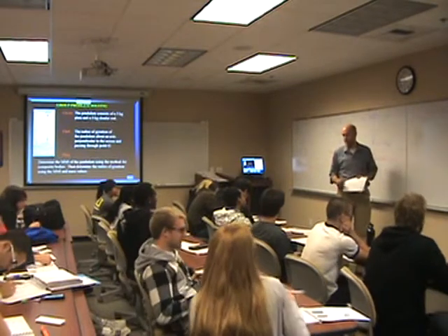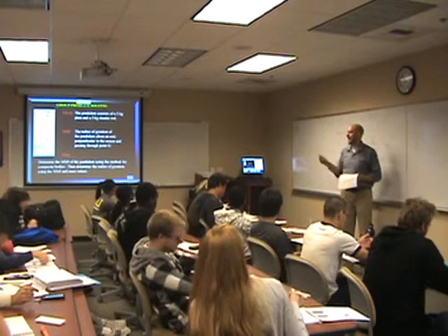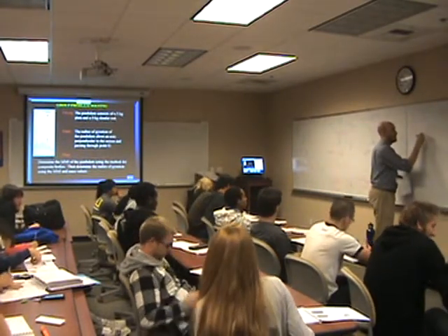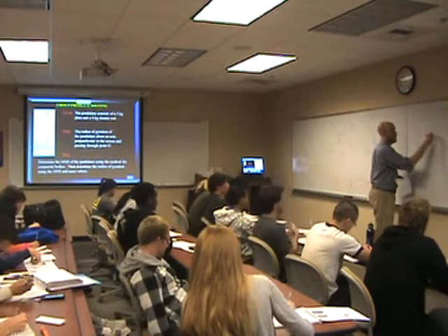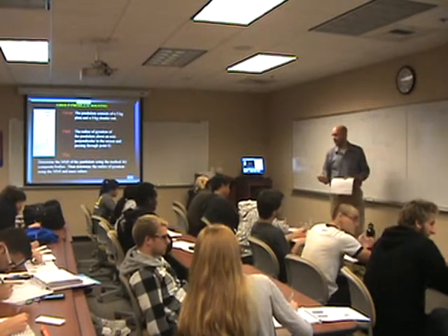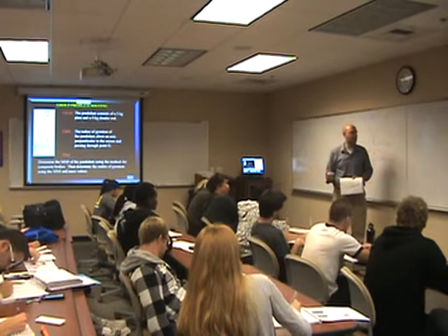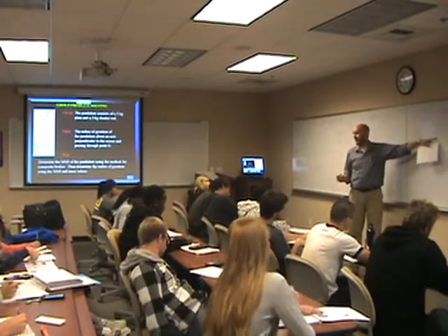IG, well, we have a rod, and for a rod we have 1/12 mass of the rod times L of the rod squared. As you get from the front or back of the book, there's a table which has these in it. So this is about its center of gravity.